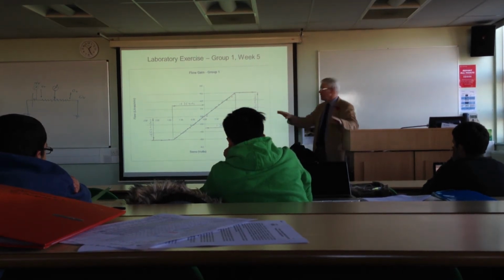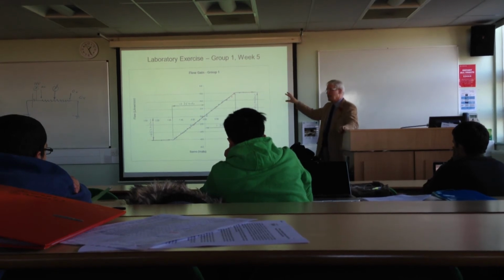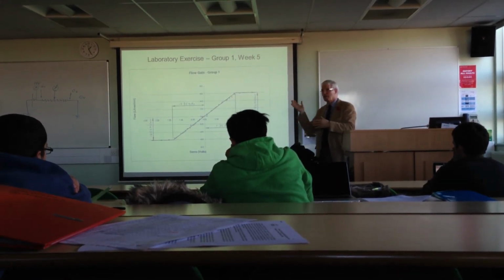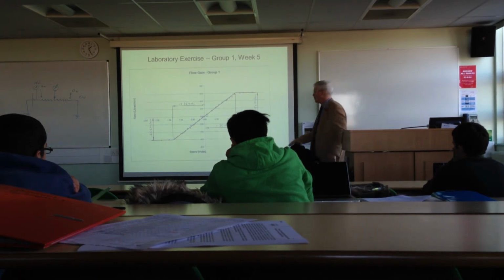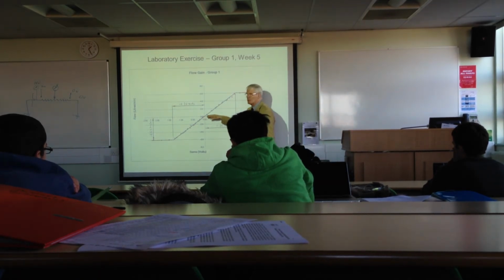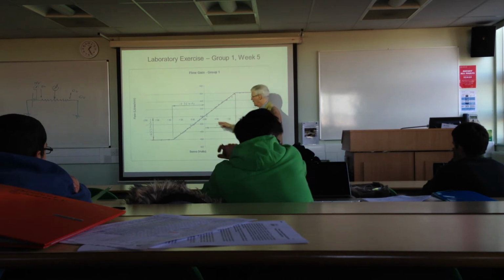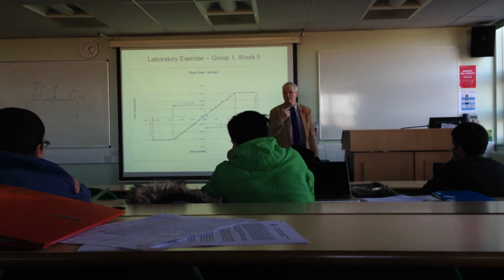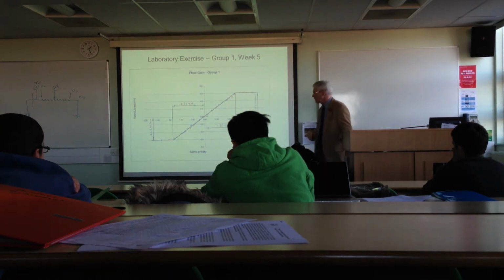Now, when you have a lookup table effectively of that sort of results, you correct for that, because we want 0 to be 0. In other words, if we put 0 volts on here, we don't want the valve to open. In this case, if you put 0 volts on, it suggests we're going to get a small flow in one direction. So you can correct that.